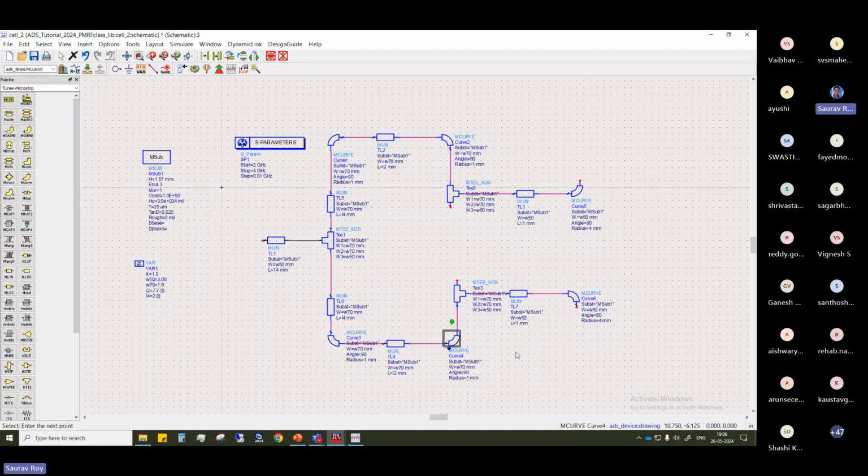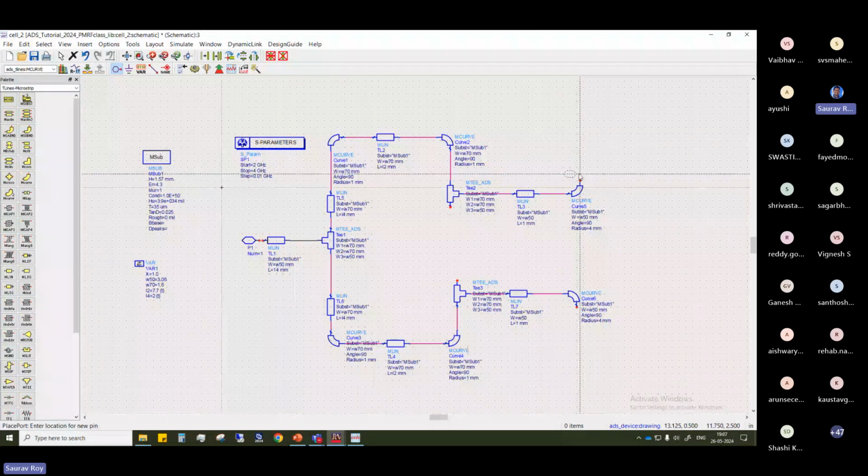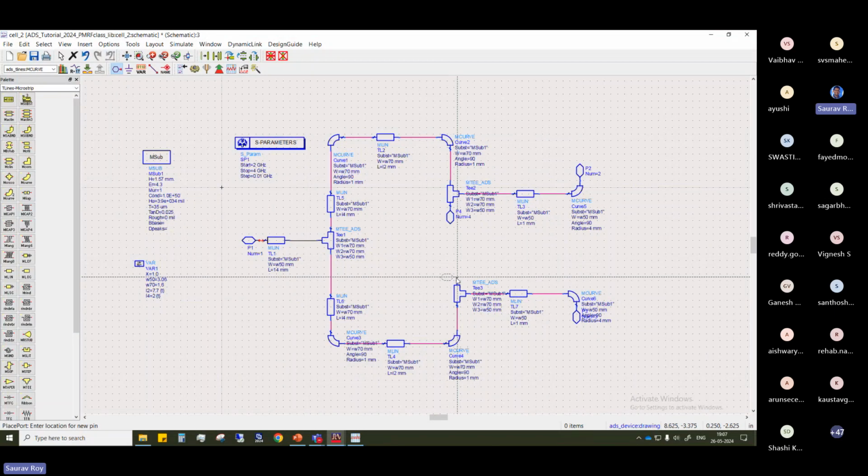Now we are not going to do it in schematic simulation. As I told you, in layout you cannot add the lumped components like capacitor, inductor, all these things. So the space for resistance we'll keep blank now. We'll define the ports here. Port 1, the port pins you can define like this. Port 1, and we define port 2, port 3, and inside also we define 2 ports.